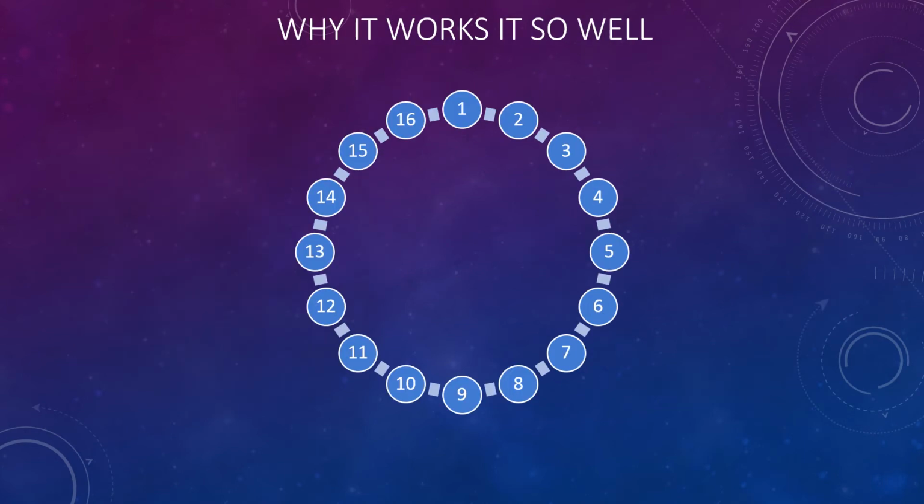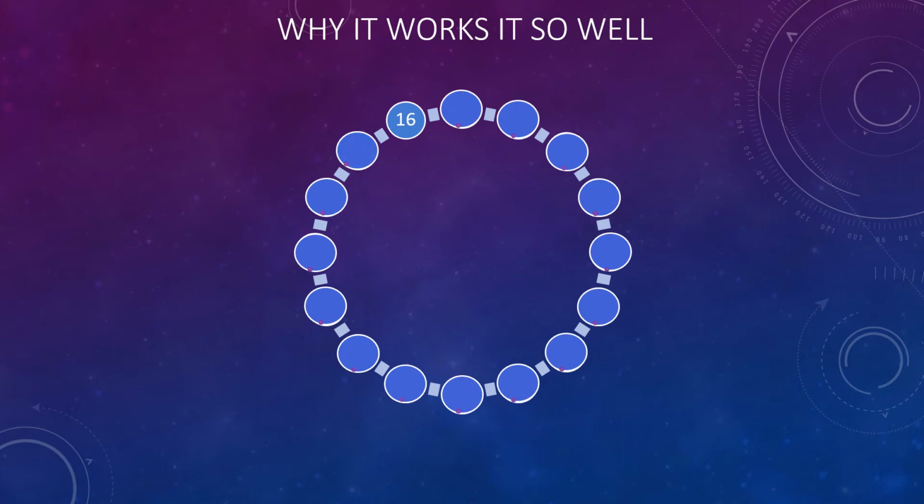So we've established that a smaller diameter or smaller radius will give us a higher velocity. And so we looked at, okay, what if we take that and expand it out? What's a good size? And so we came up with a 16 hydrocyclone separator. And basically you can see now I have 16 of these working just as hard.